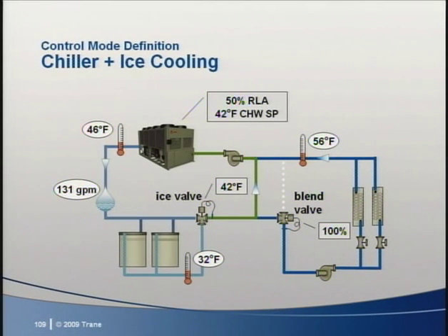There is one very neat feature of the system that we have here. Since we downsized the chiller in our design, it's actually impossible for this system to set a demand peak as high as a chiller-only system. So even if the chiller does not get demand limited perfectly, it will still save the owner operating cost.